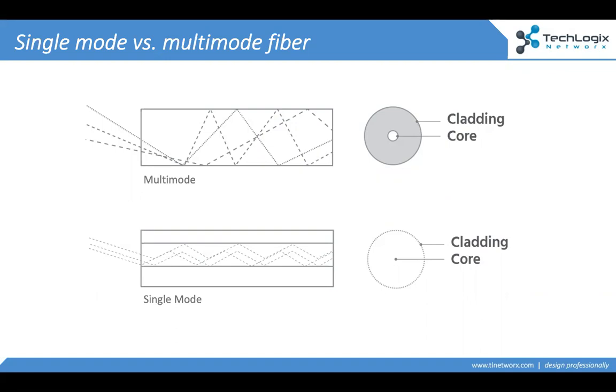With multi-mode, while the cable's more expensive, the electronics are less expensive, because we can build our electronics with bigger optical lenses, which are easier to manufacture, and having multiple modes of communication makes the signaling easier to do, and therefore the electronics cost is less.